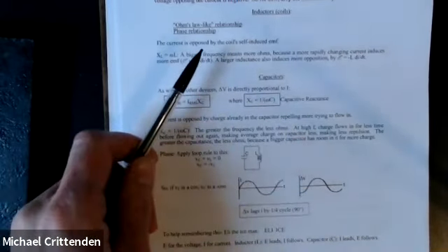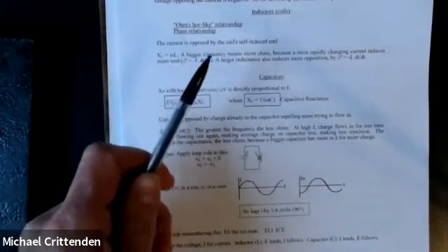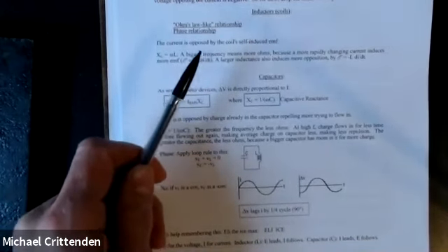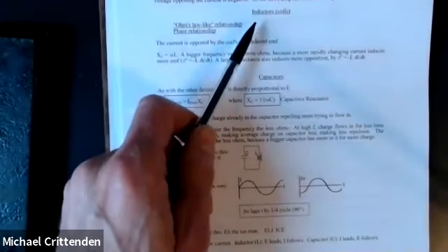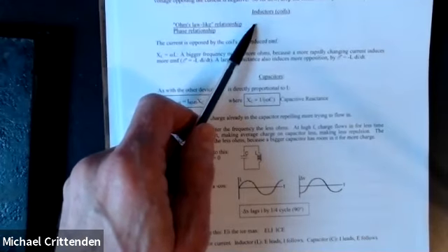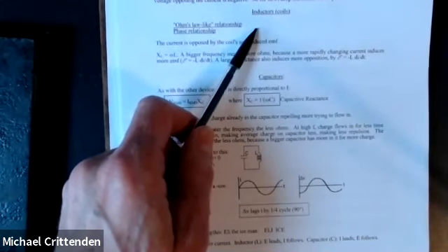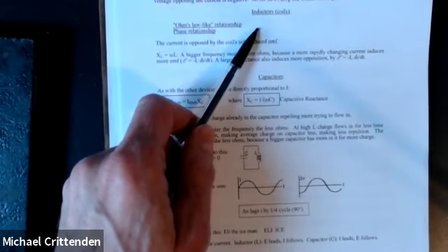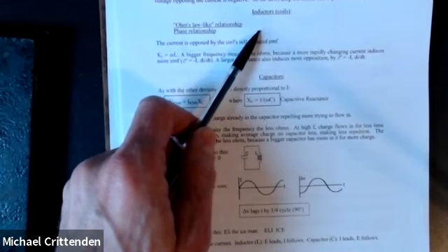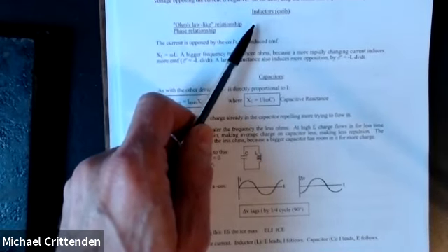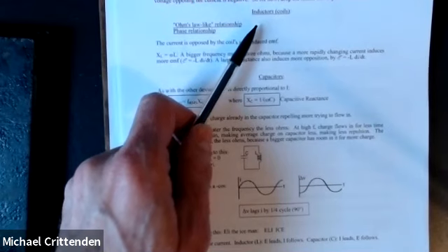Low frequencies go through a coil really well. The lowest frequency of all is 0, which would be direct current. And as I've said before, to DC, a coil is just another wire. So low frequencies slip right through it, but high frequencies have the current changing extremely rapidly, and the self-induced voltage depends on the rate of change, so you get a big self-induced voltage pushing back, and high frequencies don't like to go through a coil.